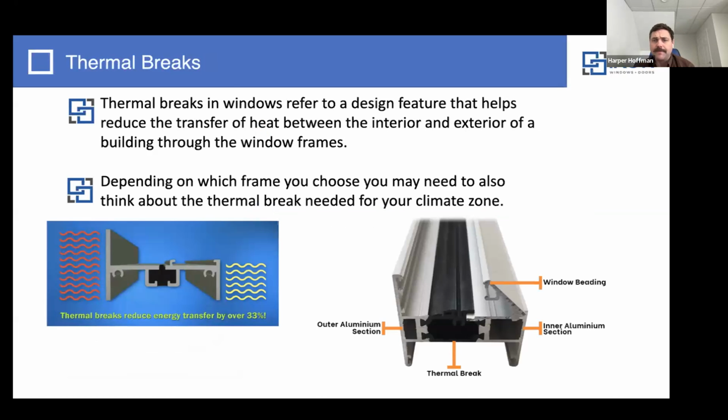So this is about the thermal break. And essentially, the image you're looking at is aluminum. That's an extrusion, you can see. And I'm being redundant because the energy is going to flow very quickly through metal. It's a very conductive material. But you want to use that for your windows to get that aesthetic you want.